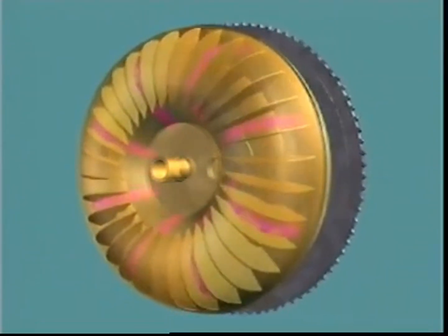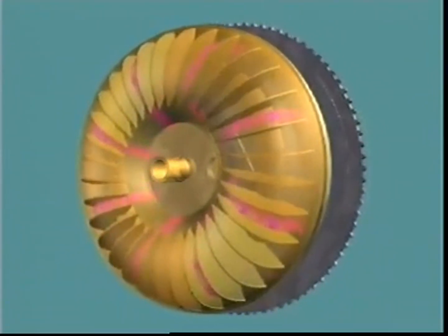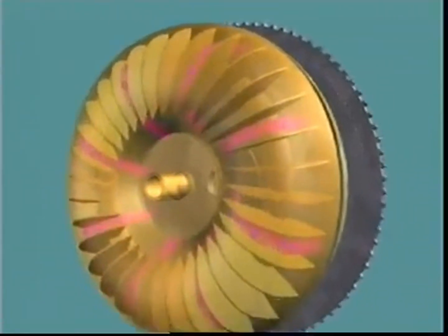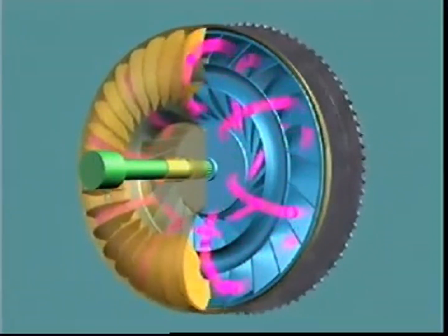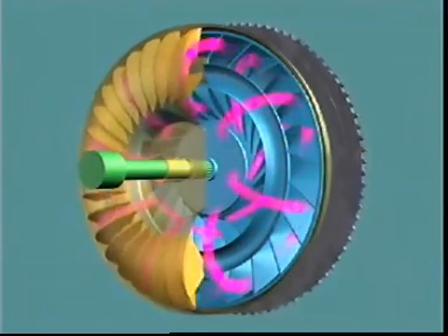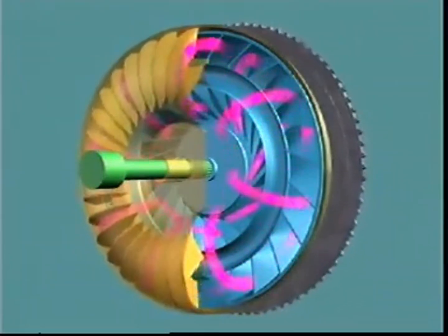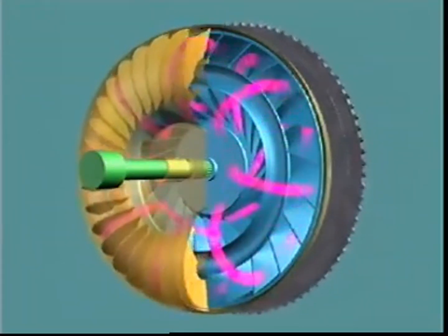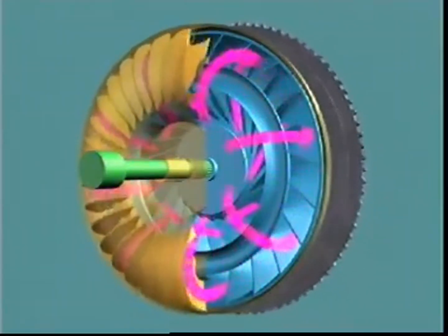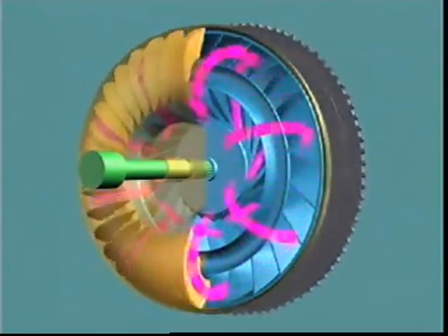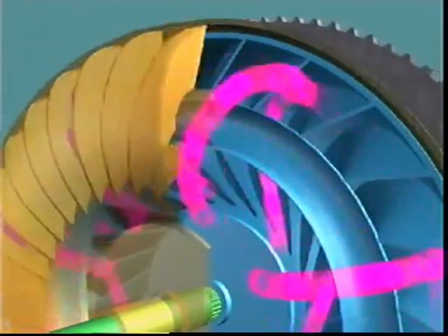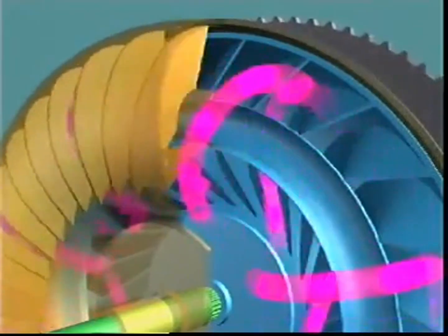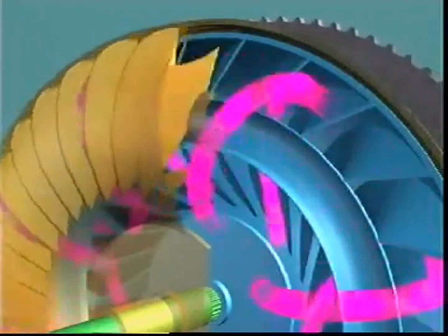Centrifugal force throws fluid between the impeller vanes outwards, around the back of the guide ring in a forward direction. This is due to the shape of the casing and the curvature of the vanes. With the engine idling and the vehicle stationary, little torque is transferred from impeller to turbine as the fluid flow is too gentle. When the engine accelerates, higher impeller speed discharges the fluid across and against the turbine vanes with greater force. Fluid exits the impeller at high velocity and enters the turbine at its outer edge.